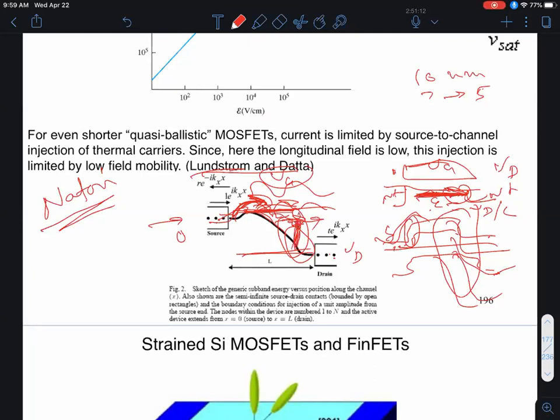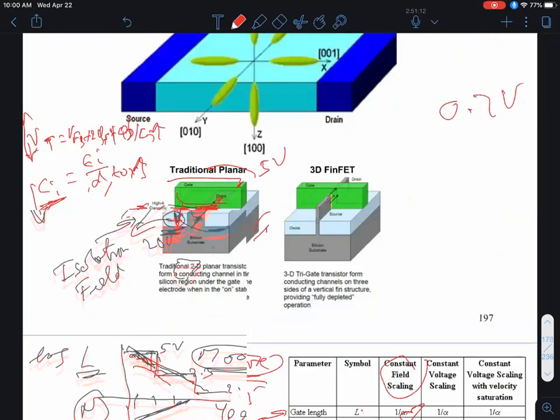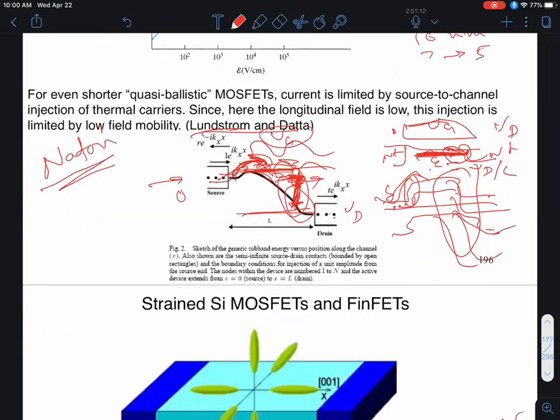You get a kinetic energy depending on the difference between the location of the electron energy and the conduction band edge shown here. Now, if the electrons gain enough kinetic energy, suppose this was my EC, and my EV would parallel that, what's going to happen? A highly energetic electron can bump into one of these covalent bonds and excite an electron-hole pair, creating a hole and a secondary electron.